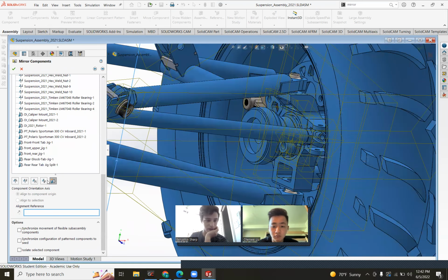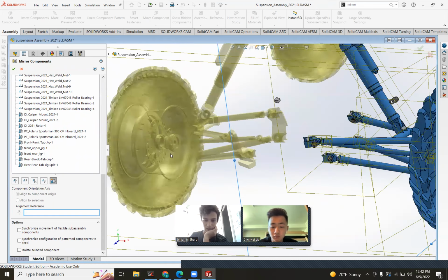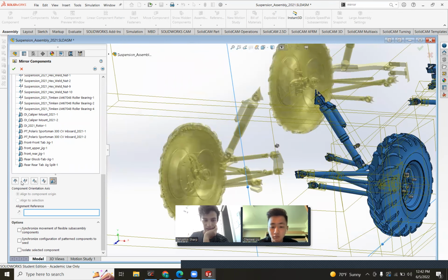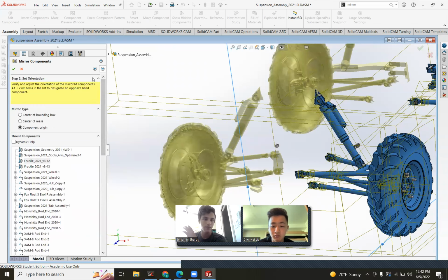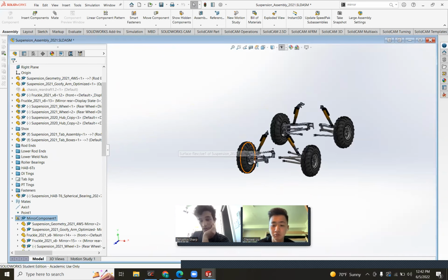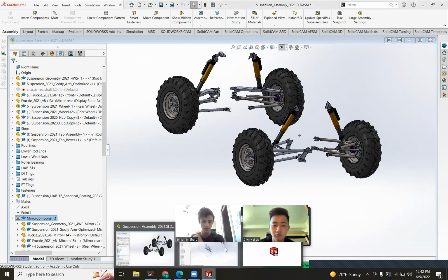For some reason, it's not being shown. But if I want to make the true mirror so that all the features are the same, but just flipped, I choose left hand. These just mirror X or Y and not both, or they flip it upside down. It's stupid. I don't know why they exist at all. But that's about it. That's the only trick. And it's also easy to flip the drawing, which I'll show you later. But SolidWorks has a tool for that as well.